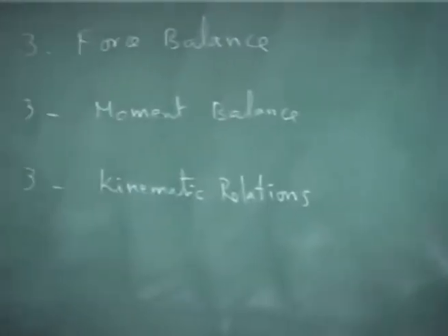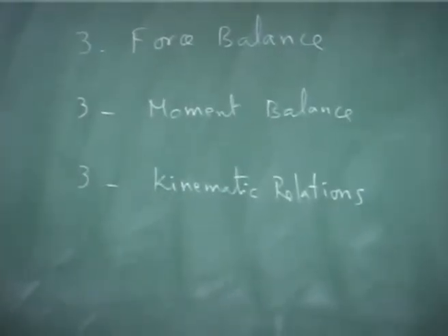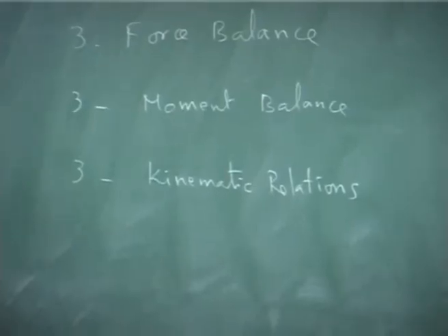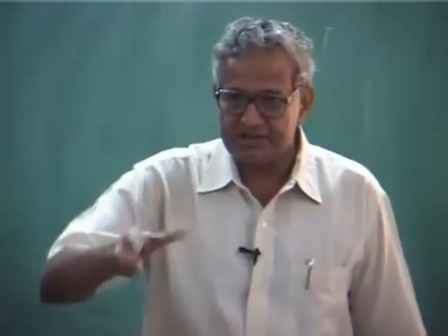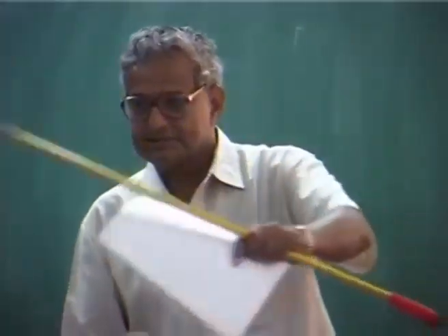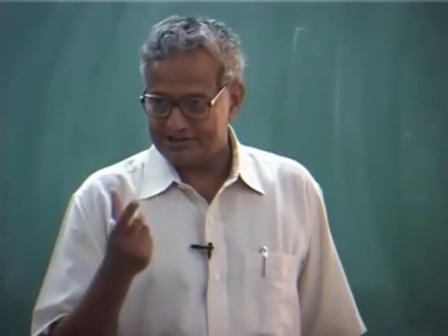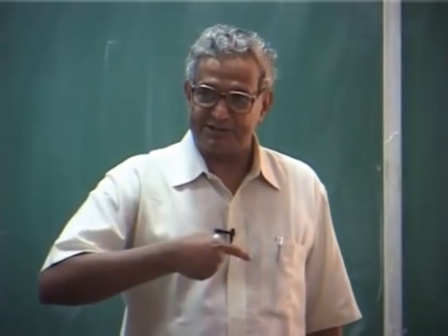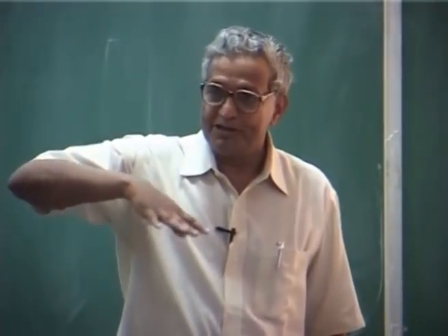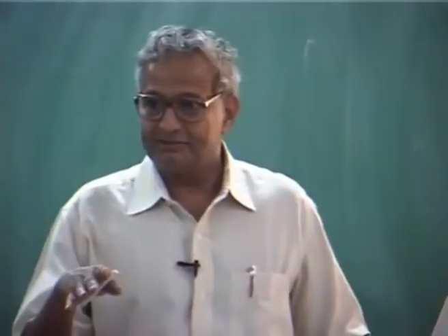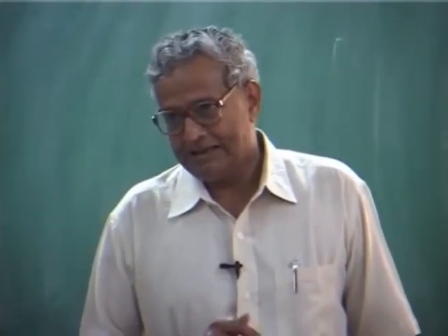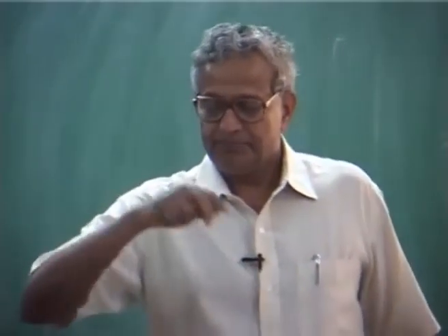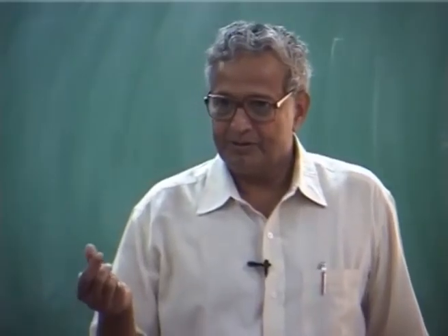But the kinematic relation represents essentially the instantaneous angular velocity, because at every instant the aircraft is turning. So it will have an angular velocity which is a vector, but how is that angular velocity vector related to the orientation rate of the helicopter with respect to some earth fixed coordinate system? Orientation of the helicopter is one, angular velocity is another, how do we relate this?